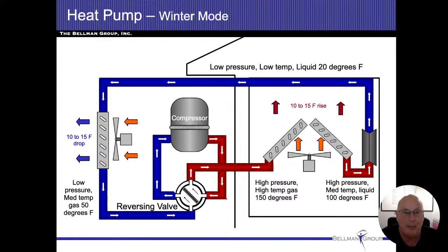Cause it to boil, so now my outdoor coil, which used to be my condensing cabinet, is now my evaporator cabinet, because now I'm causing it to boil, change back to a gas, gas comes to the compressor, and so forth. So a heat pump, or I should say an air conditioning system, is technically a heat pump, all right? But when we use those terms, the difference between a heat pump and an air conditioning system is that reversing valve. In this diagram, you see it on the bottom there, and that changes the direction.